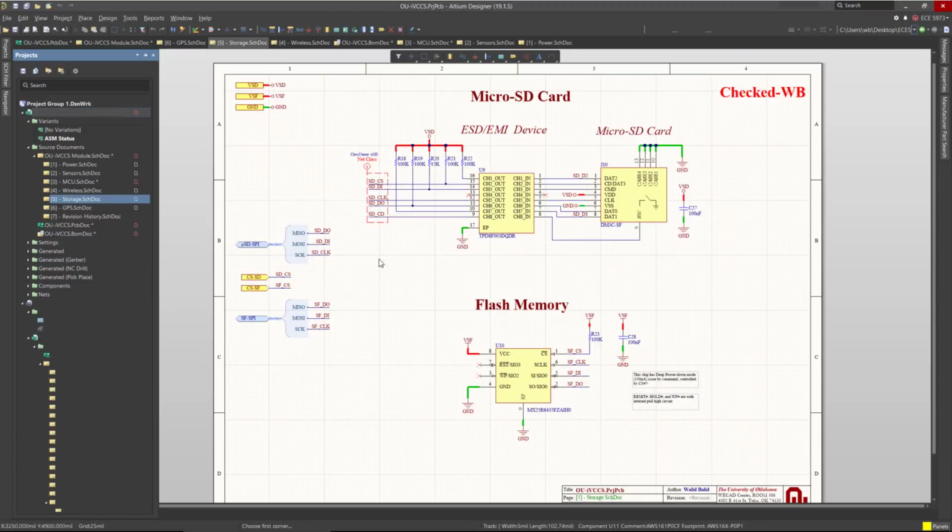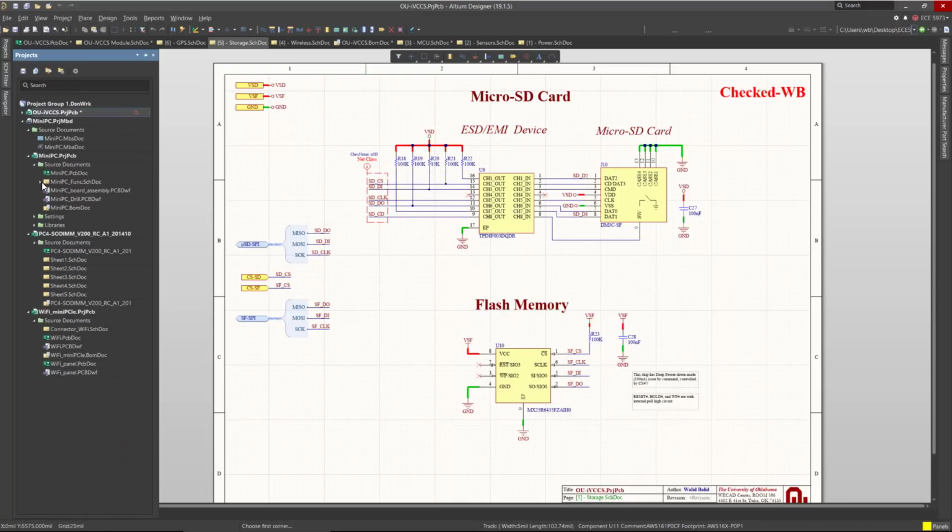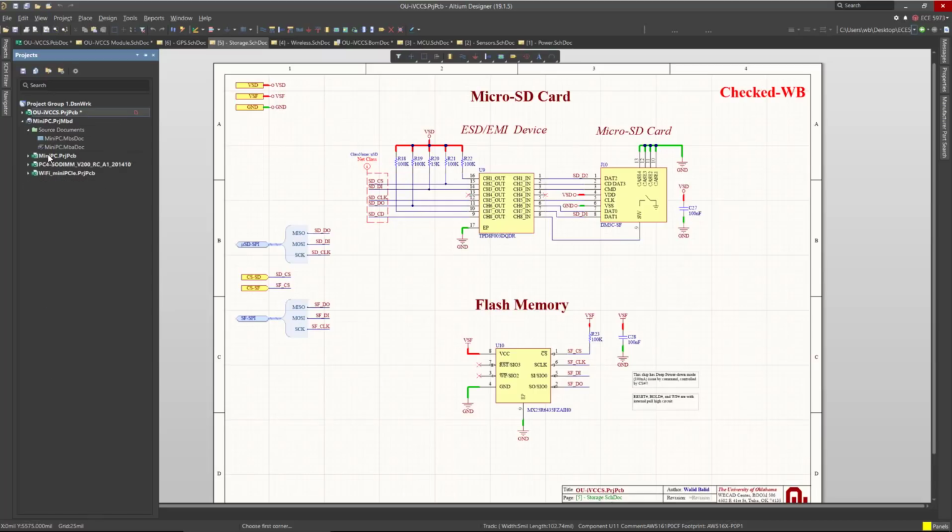If you open it, that's this one. So inside this one, you can see how many projects you have. You have 3 projects combined within one called multi-board project. The reason for that: if you are designing a motherboard and you need to fit on this motherboard, let's say RAMs, a graphic card and so on, and you need to see how they all fit together, especially when you design an enclosure and you are doing clearance analysis, in this case you need to use multi-board